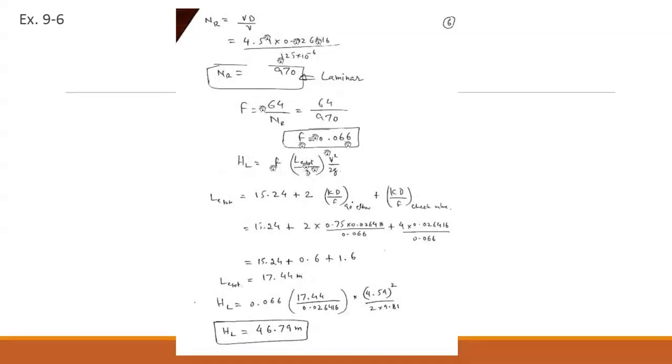So F, which is the friction factor, times the equivalent length, total. Total why? Because equivalent means that you add the length of the pipe to the equivalent length of the check valve and of these two fittings. So that would be just added, all in this one. The diameter D is the internal diameter of the pipe. Again, V squared is the velocity, and 2g, you know that.